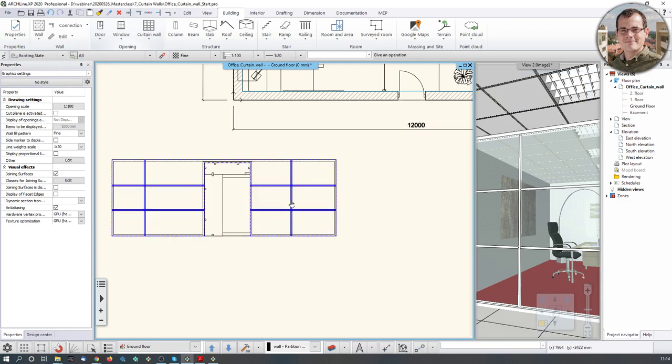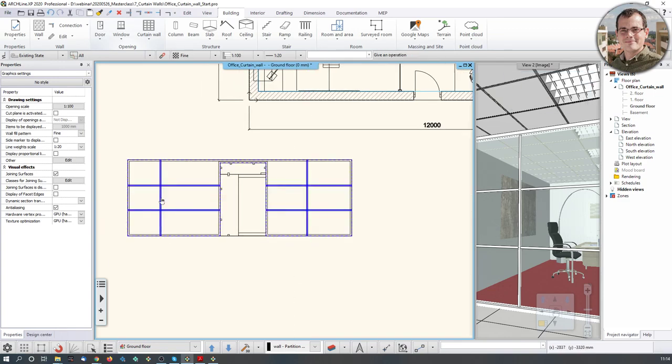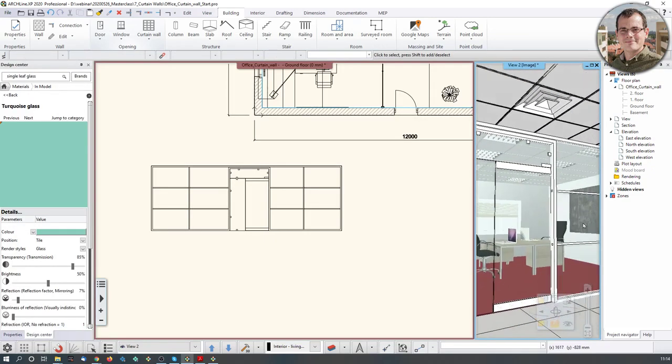So we know that this mullion is now 1400 from the corner point. Let's amend the other one as well, so make sure that it's nice. Let's just hit the tab key until it goes into beginning, and 1400 would be fine. So I think it's symmetrical to some degree. So let's go to the 3D and admire what we have done. I think this is good enough.